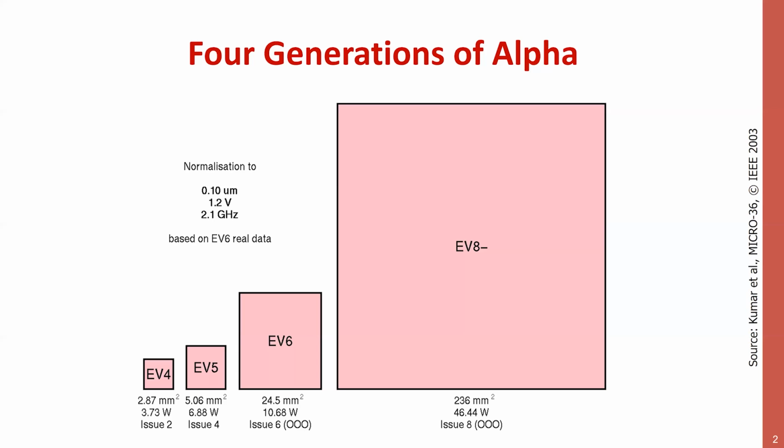The idea is to look at the silicon real estate, so how big these processors are. What is very peculiar is that whenever these processors came out, they probably were around the 2 square centimeters that typically processors are. Why 2 square centimeters has to do with yield, right? You want to have processors that use as much as possible the technology that you have to be as performant as possible, but they cannot be too large a die because otherwise yield goes down, right?